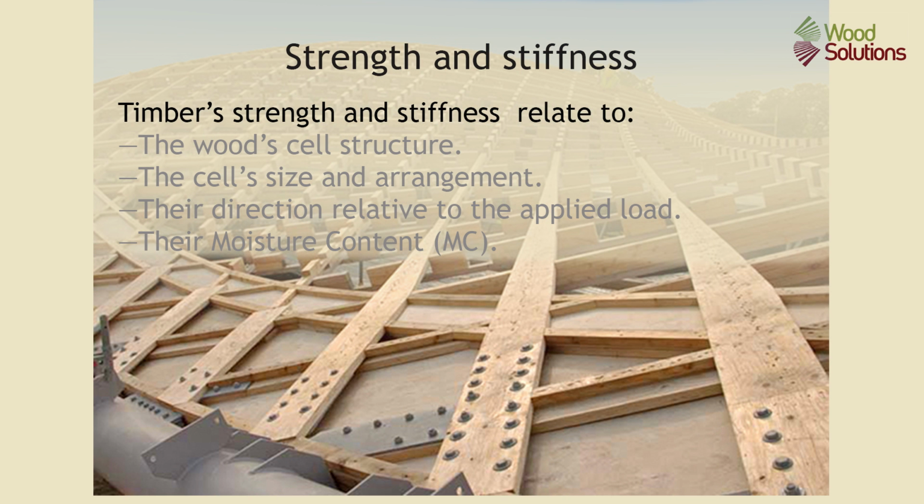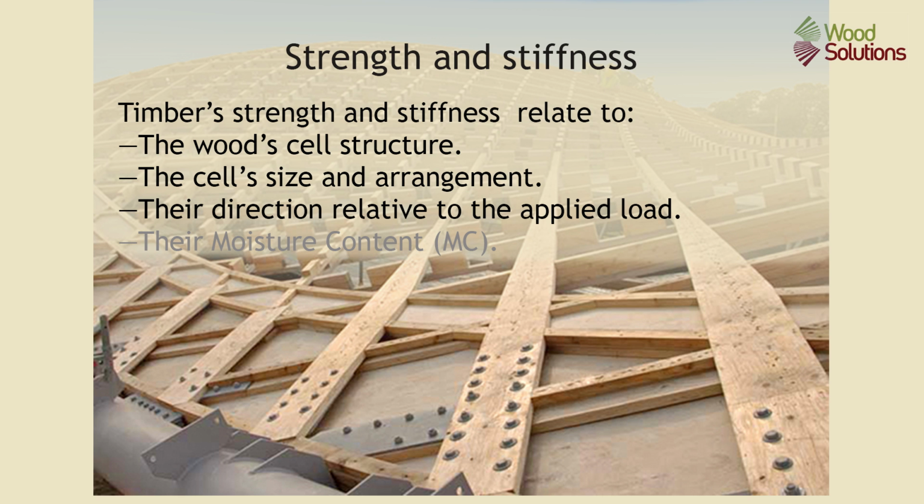Timber's strength and stiffness are related to the wood's cell structure, the cell structure's size and arrangement, and their direction relative to the applied load, and finally to their moisture content.